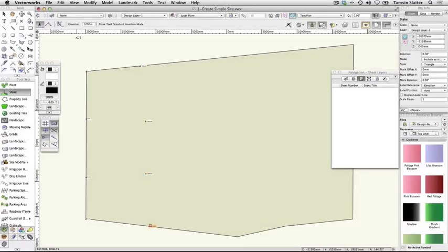On the toolbar, change the elevation to 2500 millimeters. Roughly halfway along the shape, place another vertical arrangement of 4 stakes on the polyline. On the toolbar, change the elevation to 3000 millimeters and place a further arrangement of 4 stakes, roughly 3/4 of the way along the shape.